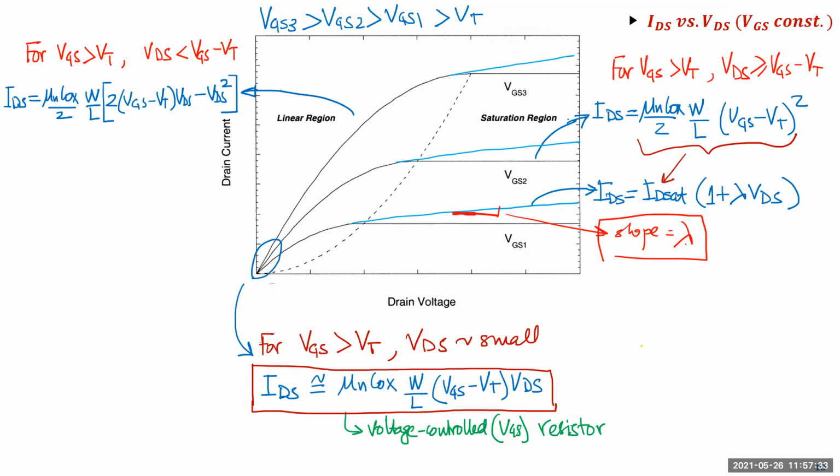Will the graph of IDS and VDS not be a downward parabola as there is a VDS squared term in the equation? Well, that's what I explained, right? Physically, it is not possible. So that's why we said physically why it is going to be constant, and then we said, okay, it's not exactly constant, but it's going to vary slowly, and that slowly varying term is an empirical term which is adjusted.